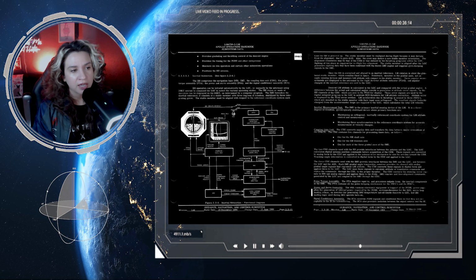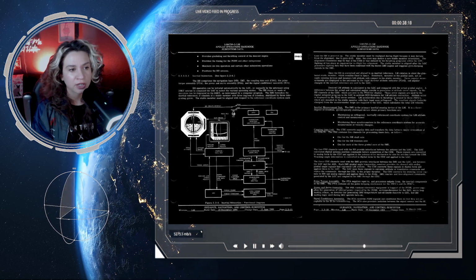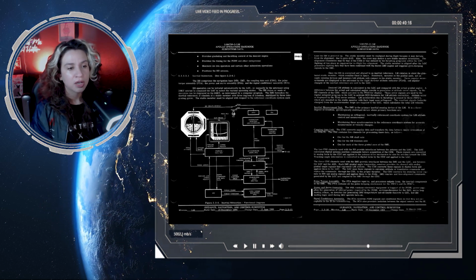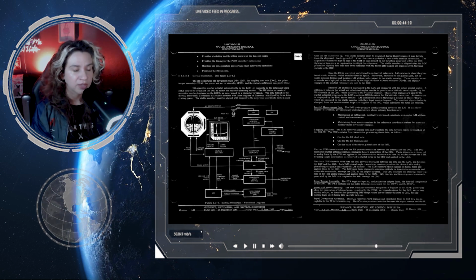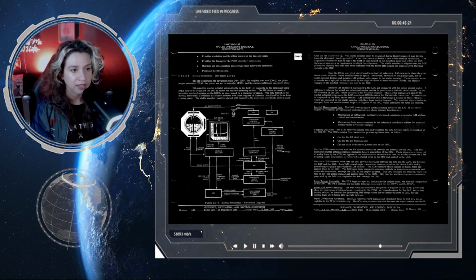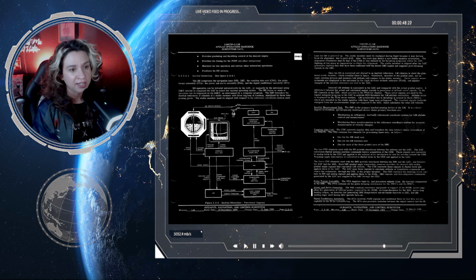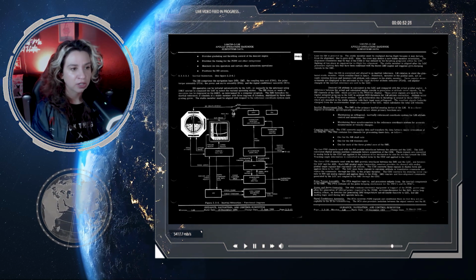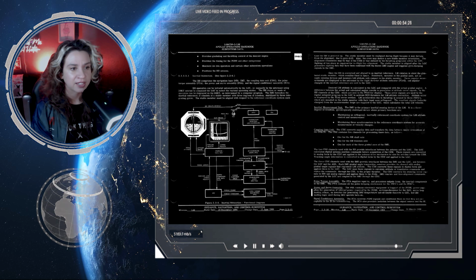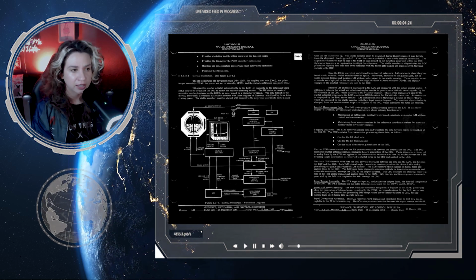The LGC calculates digital antenna position commands before acquisition of the CSM. These signals are converted to analog form in the CDU and applied to the antenna drive mechanism to aim the antenna toward the CSM. Tracking angle information is converted to digital form by the CDU and applied to the LGC.